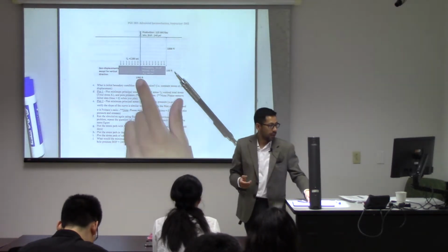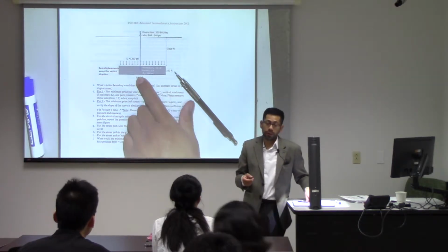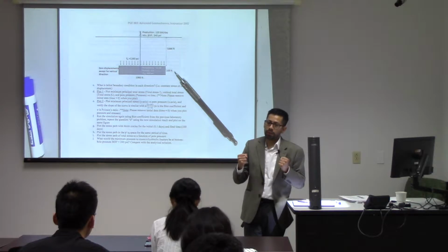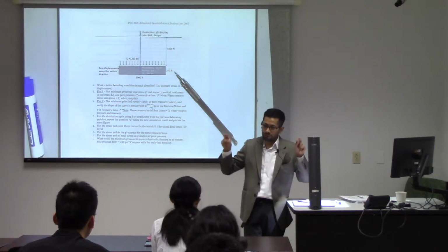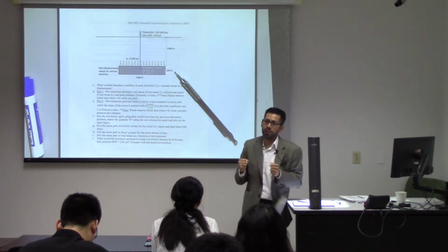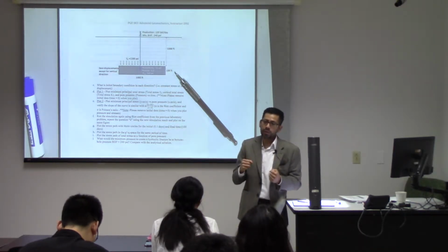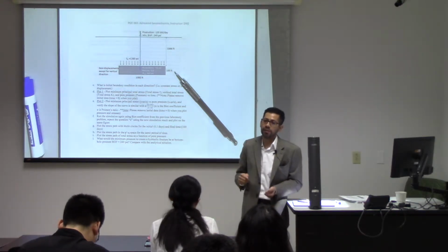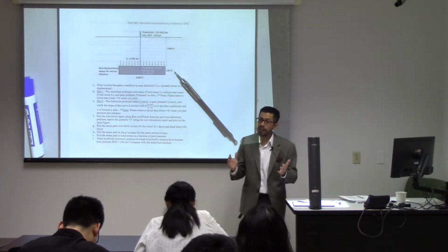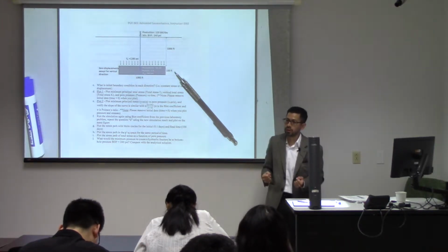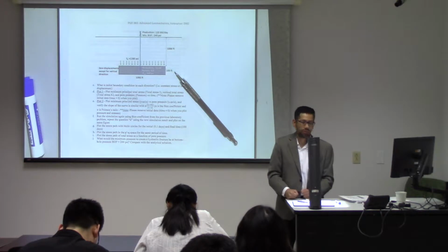In this case, when you have a porous solid, we're going to be adding stress to the rock, but with no addition of total stresses. We're rather decreasing the pore pressure, and that decrease of pore pressure is the one that is going to increase the effective stresses. So we're not adding anything. Furthermore, we are extracting fluids, and that's causing the change of stress.